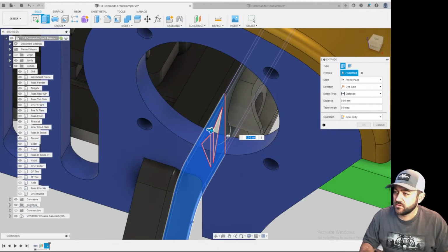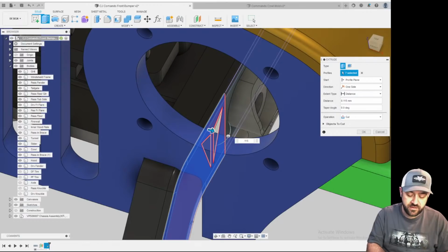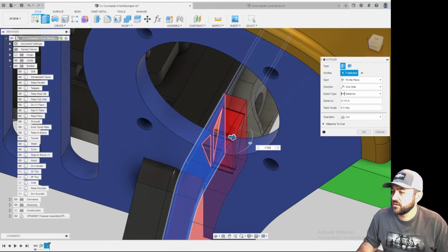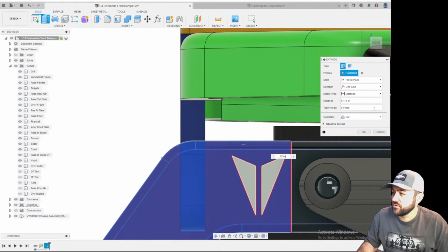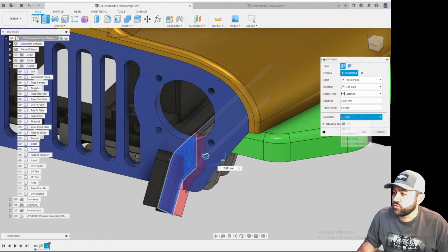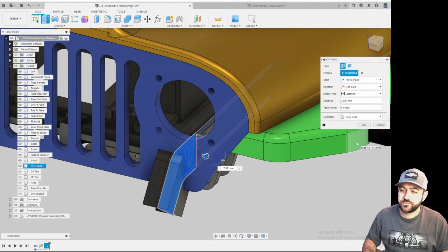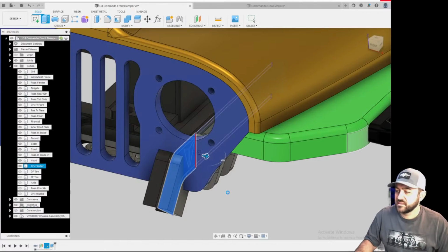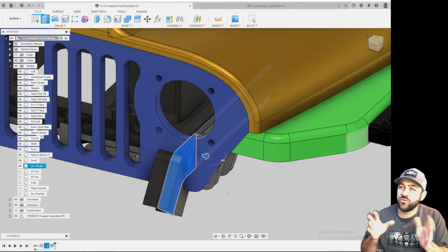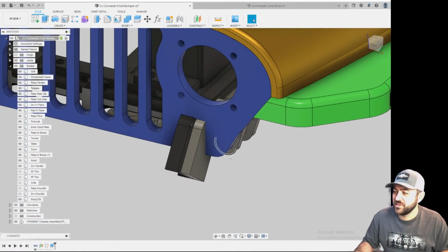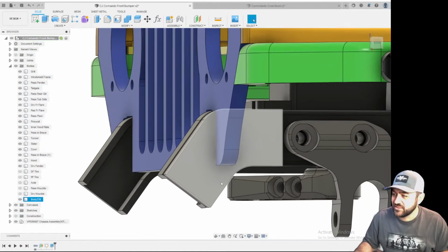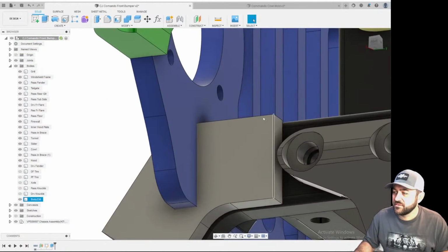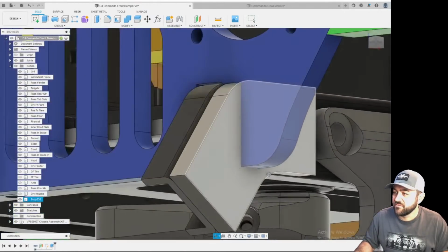I'm just going to go 0.115 inches. Oh, it's going to put a V logo in there for me, which is not what we want. And I'm going to do new body, of course. And it's going to make us watch it think for a minute. I don't know why it does that only when I stream. It's not even a CPU usage thing. It's just odd. So basically I was just creating a little plate here to give myself a base.